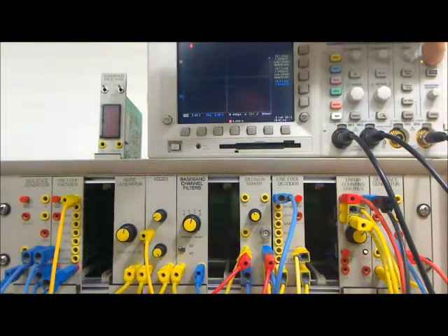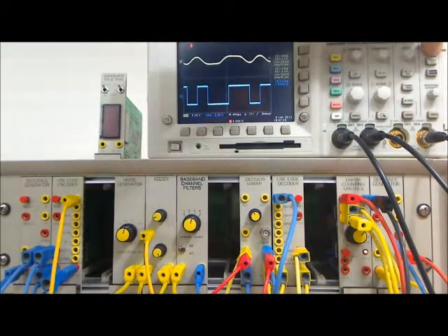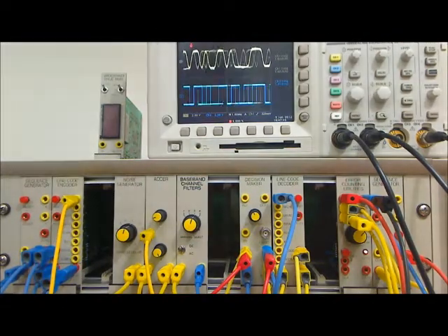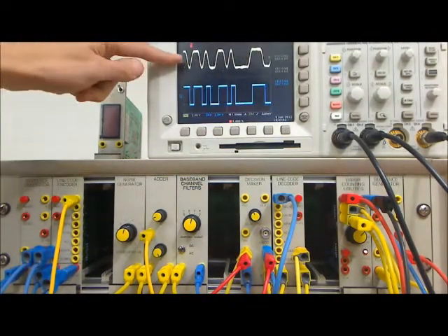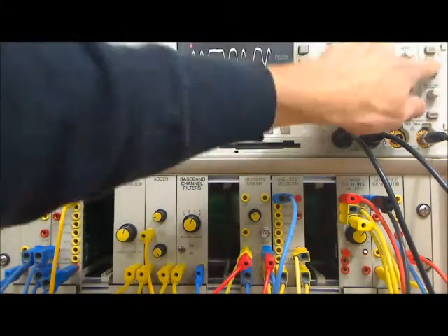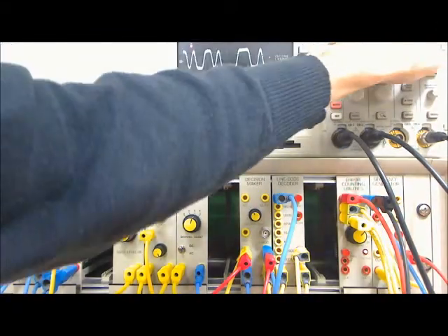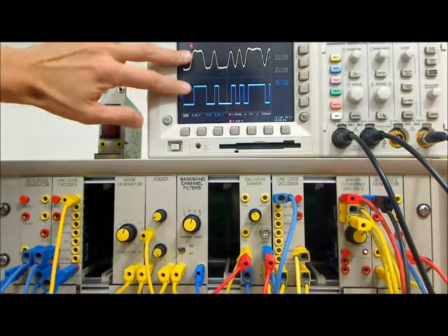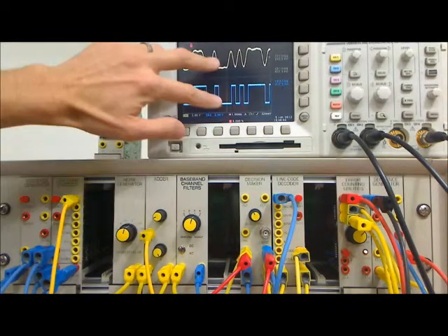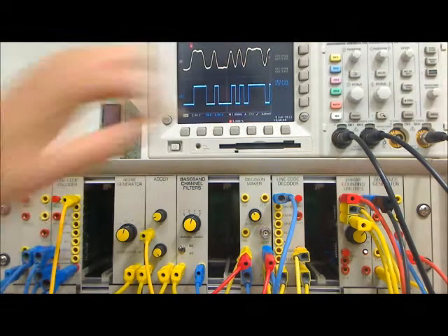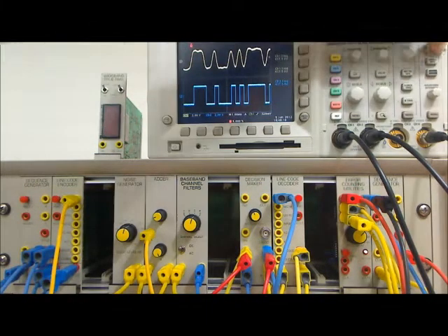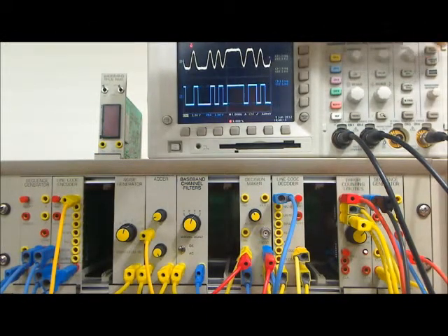Turn off the signal. Use single shot. We can see channel 1, make some changes. At the top we have the band limited input, and at the bottom we have the output from the decision maker. You can see they correspond: 1, 1, 1, 0, 0, 1, 0, 0, okay. And without any significant noise, the correspondence is there.